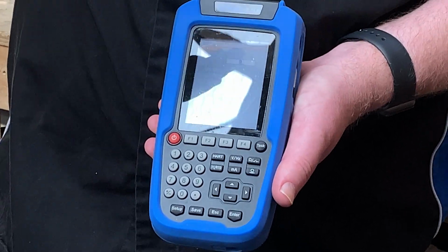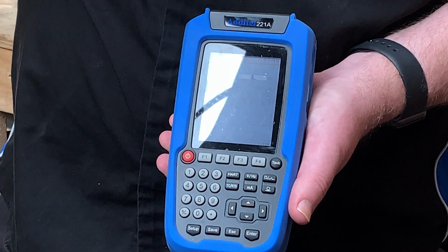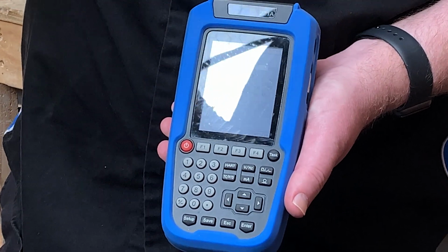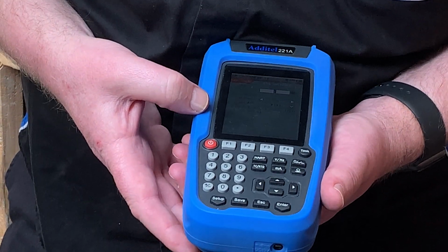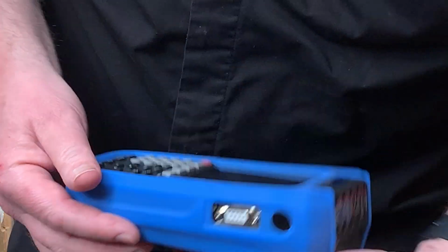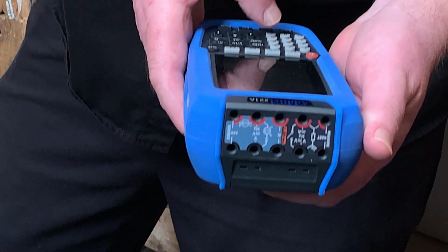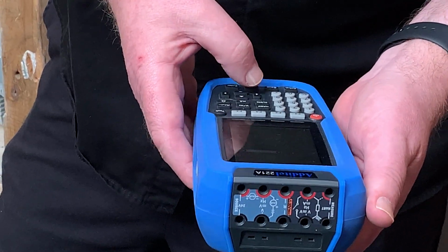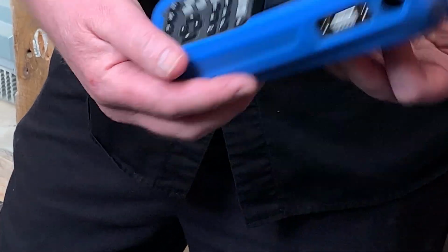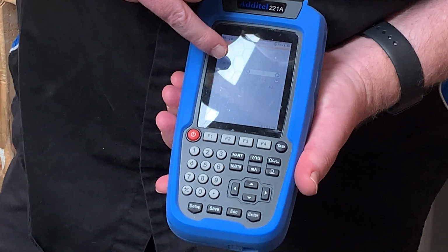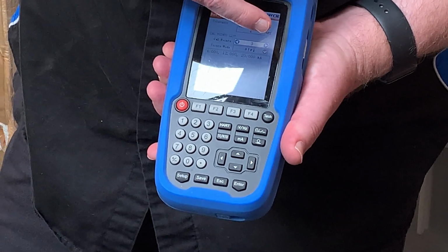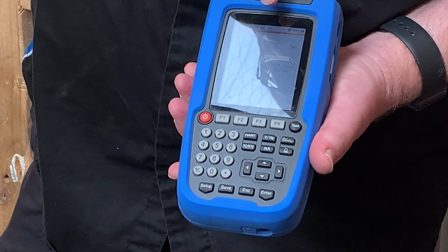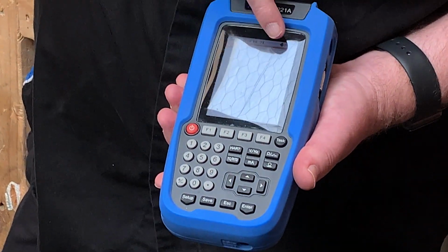So this is for if you're doing an actual calibration. No one's going to do 12, no one's going to do 2. Most people are going to do 3 or 4. So what's it got in there at the moment? It's got 5 calibration points. Let's do 3. So it's going to test it at 4 milliamps, 12 milliamps, 20 milliamps. And we've said that 1% is the acceptable tolerance.